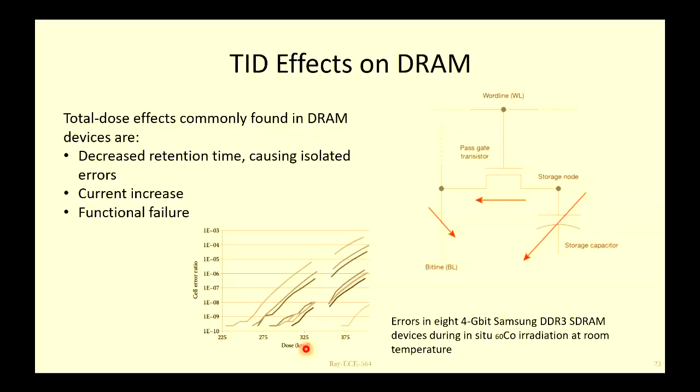Yeah, so I'll finish it off very quickly, but do you have any questions on radiation effects on DRAM? Radiation effects in flash, radiation means total ionizing dose effect, right? TID effects are predominantly more for flash or non-volatile memory like flash because it is a slow, parametric effect. Whereas for DRAM, you will see the single event effect, which we'll talk about next class.